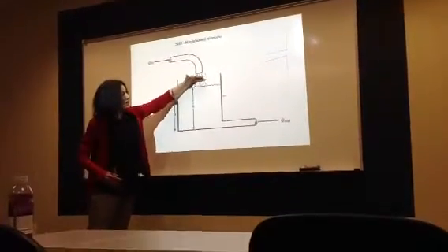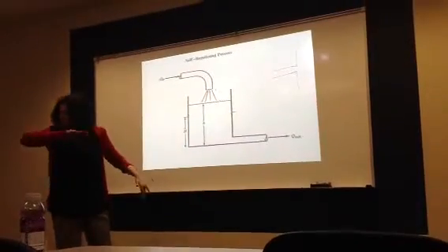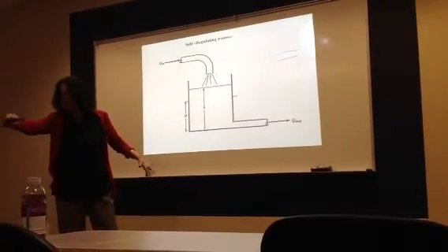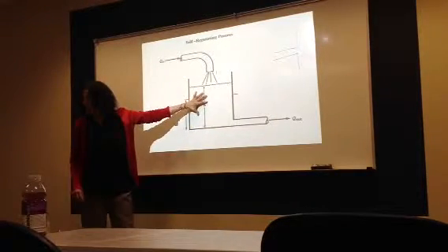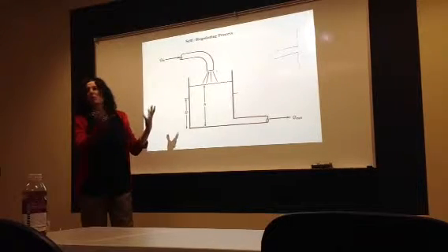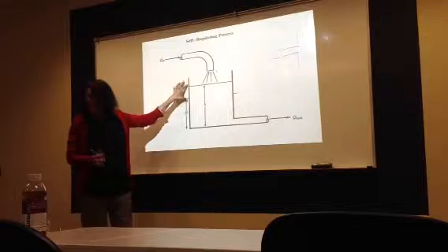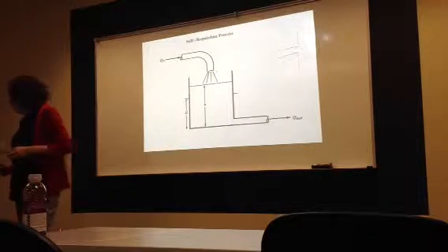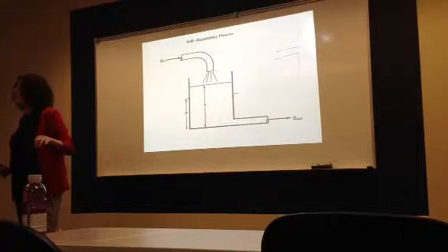As the tank level increases, what's going to happen to the flow out? More pressure. Because the flow out is proportional to the head pressure of the tank, right? So the process will be stable without any feedback control. You understand that, okay? So that's number one. That's chapter one, by the way. If you look at all that in chapter one.